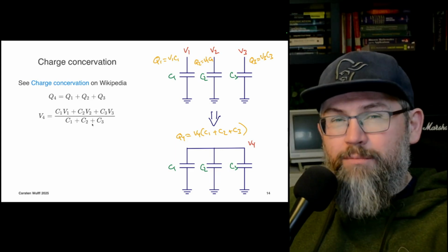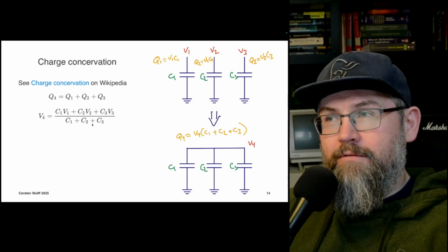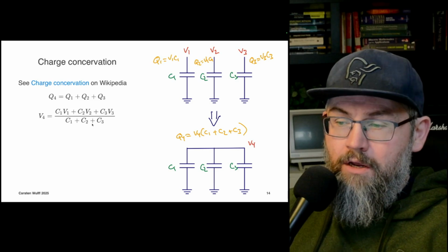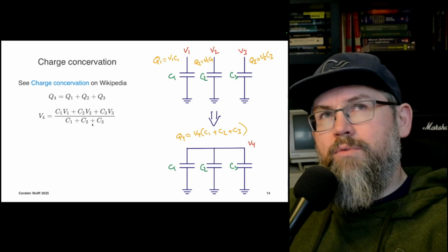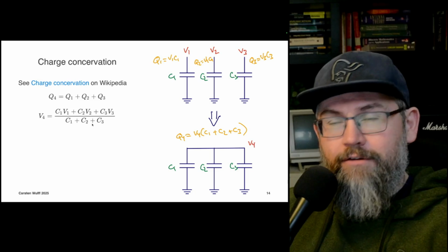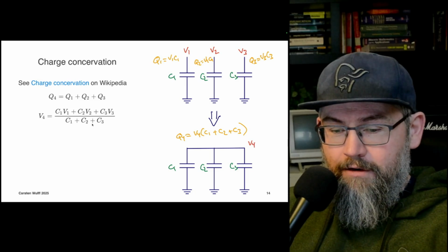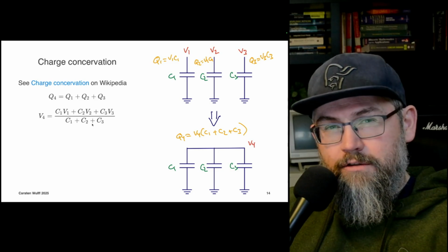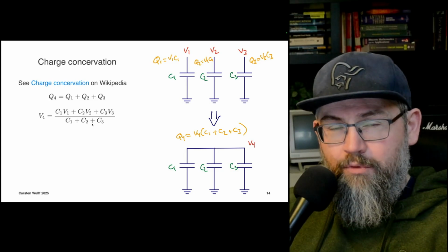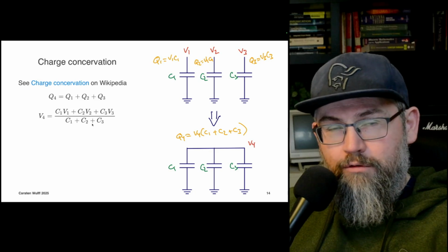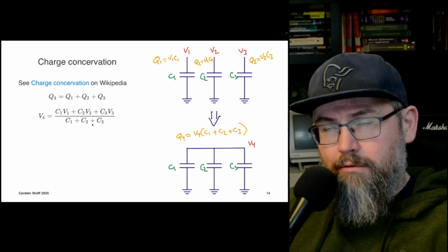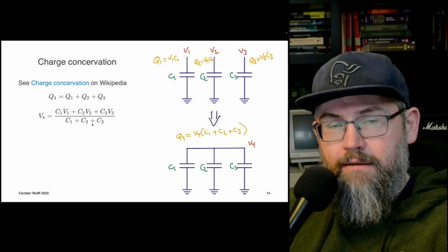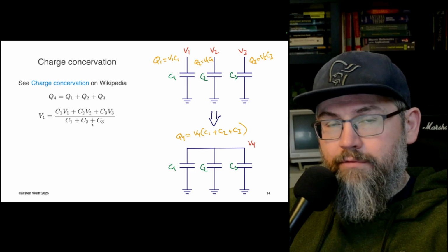Okay, so these are a few methods that I could think of for how we can sum stuff in analog electronics. And I think the key, you can do it with op amps and resistors and so on, but that's going to be quite large circuits. As soon as you introduce an op amp in order to force two nodes to be the same voltage, then that's a quite significant increase in complexity. It could be okay if you only have one sum.